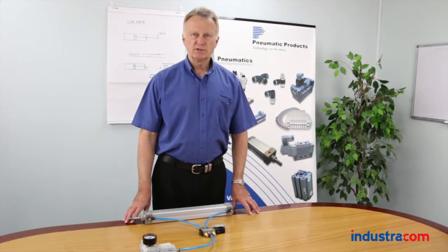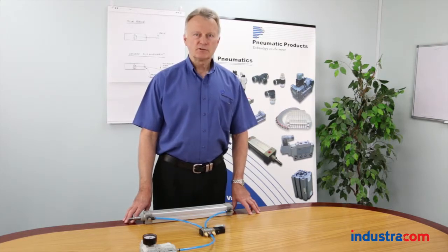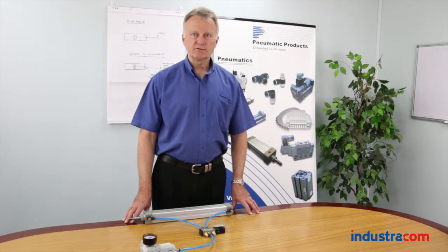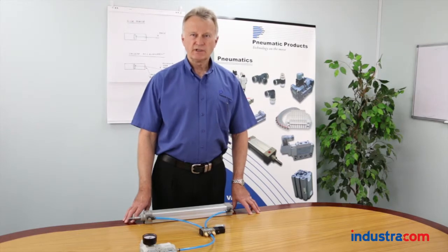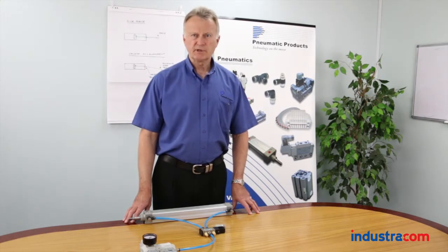The first thing would be the source of that air, which is coming from a compressor, and is the compressor coping with the system demands? Not only the demand of your machine but also of the factory. It could be that new machines or new equipment have been added, using more air, and the compressor is struggling to keep up or cope. So this is one consideration we need to look at.